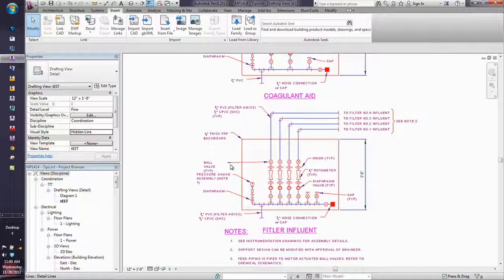Because what's more important to us, the color or the line weight? So you want to go through and have those line weights assigned. Now this, again, only works when you do an explode. And the only time I really do this is when I have a cleaned up detail in AutoCAD that I've already purged and wiped everything out. So it's a good habit to do that with your AutoCAD stuff if you're going to use that over and over again. It makes it a whole lot smoother, and a lot faster to make it comply with your standards.